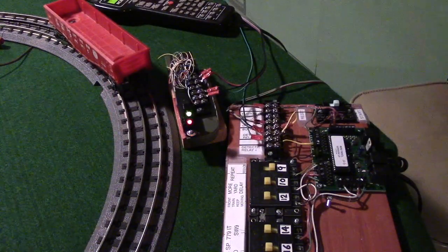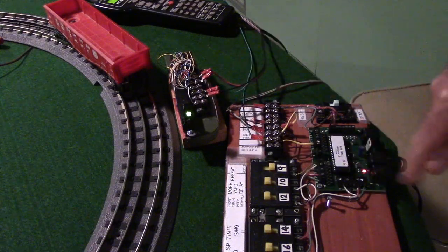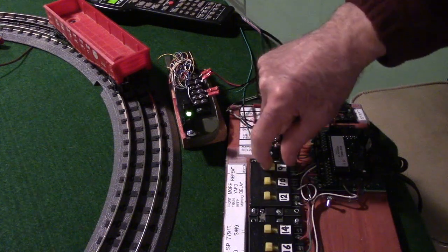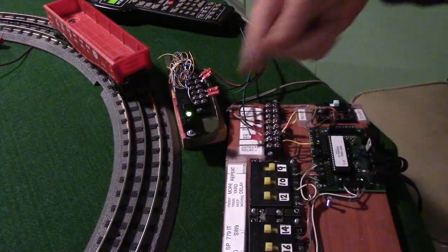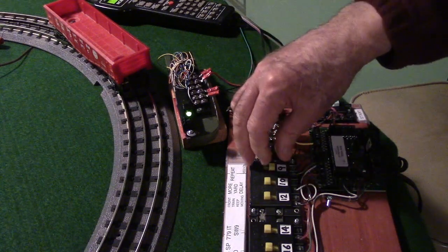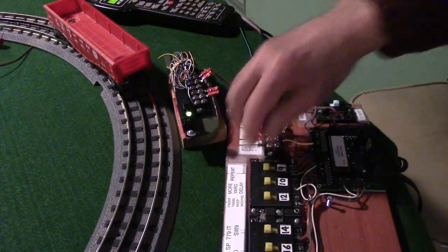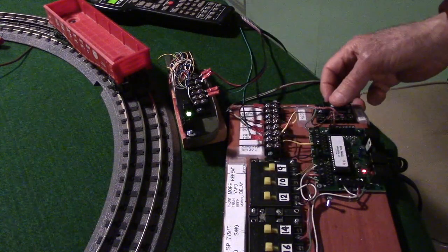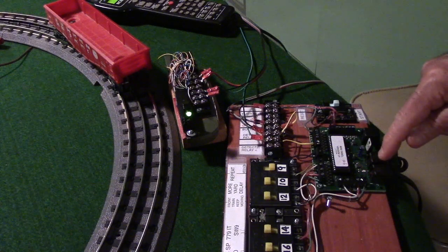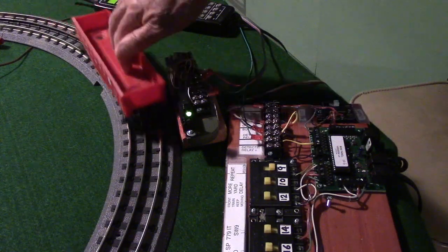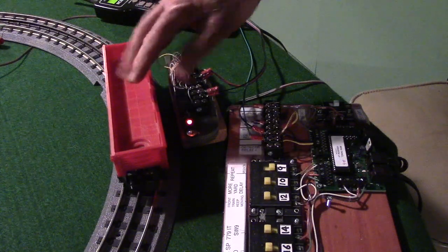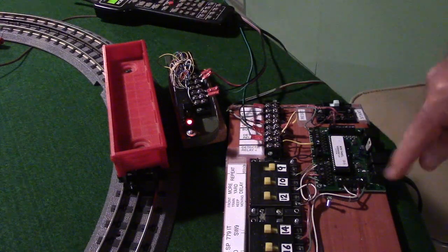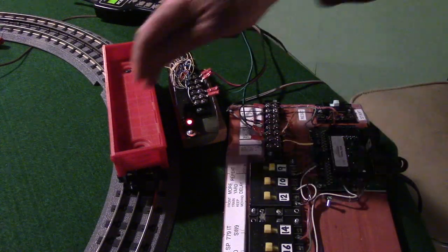If we move that car away such that it goes green again, you can see it goes back to its regular speed. And we got to have the repeat switch closed to do this, because it's repeating the program about twice per second. And if we open the repeat switch, it quits and stops. If we close the repeat switch and start it up again, it'll start blinking again. But using this, we can test the detector again. If that detector goes to red, it closes the relay, which is back here, which adds an extra delay to that blinking and slows it down.